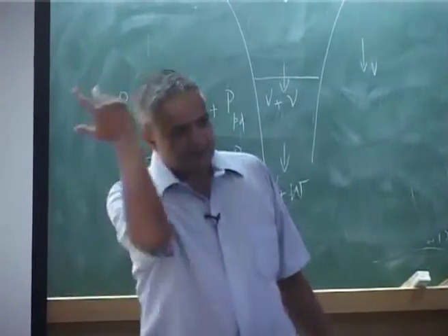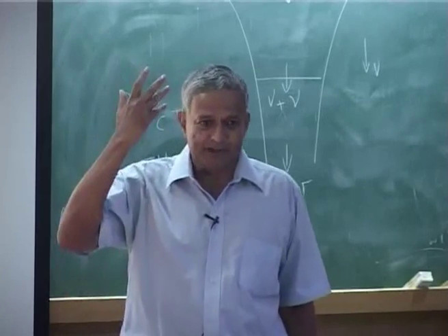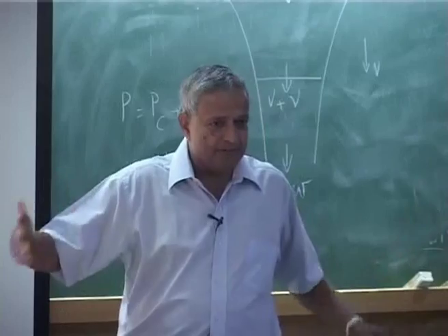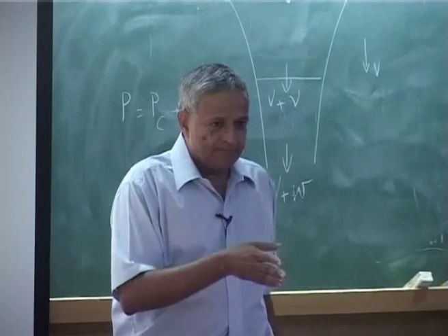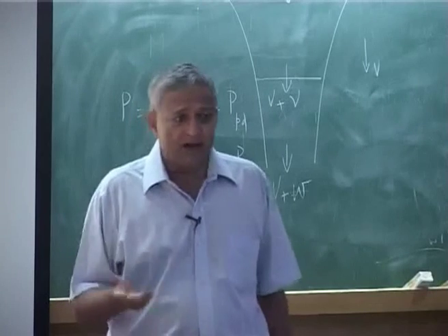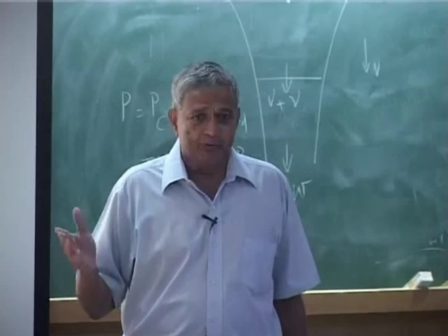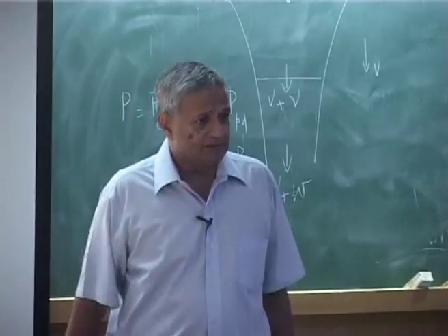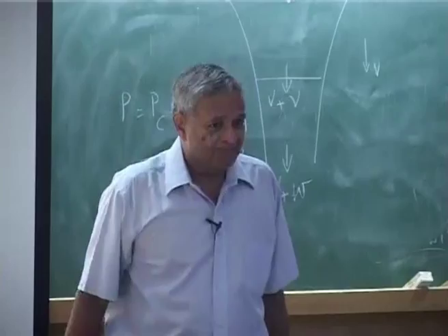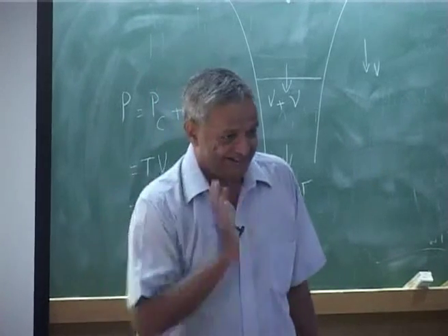Suppose you keep increasing your omega, what will happen? Your stress will go tremendously, because for most of the blades, for the operating omega, the root centrifugal force is of the order of 100,000 Newton. Now you double it, it will become 400,000 Newton, that is all, the whole blade will start flying all over the place. You understand?